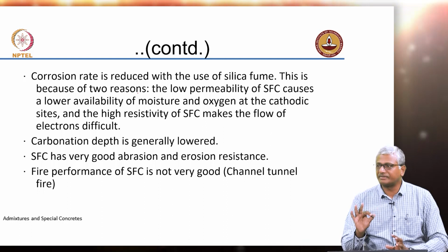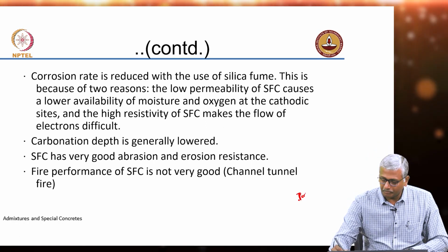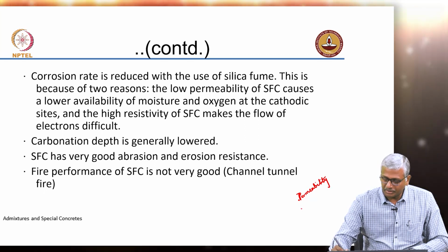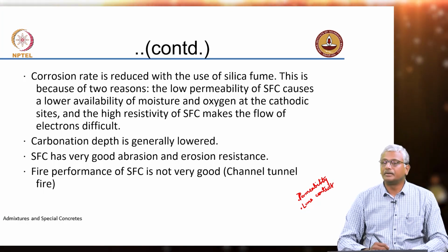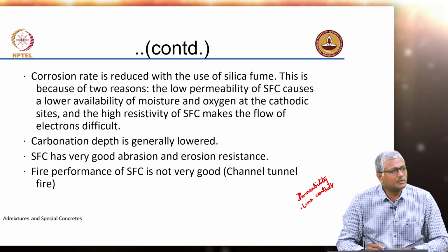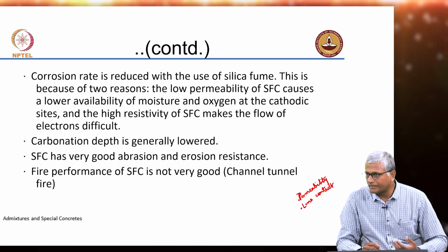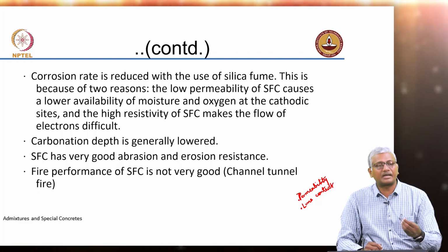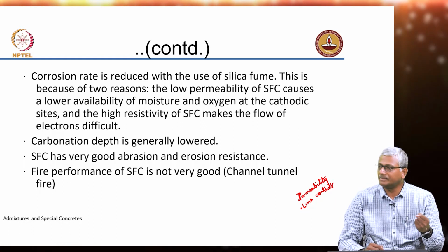So, there are two effects at play here, right. One is permeability, the other is your lime content or calcium hydroxide content, right. In the case of silica fume, we use very little of it, and a lot of it may not even get a chance to react and may be simply functioning as a filler. So, silica fume, although it is a highly reactive pozzolan, is going to consume calcium hydroxide to some extent, right.